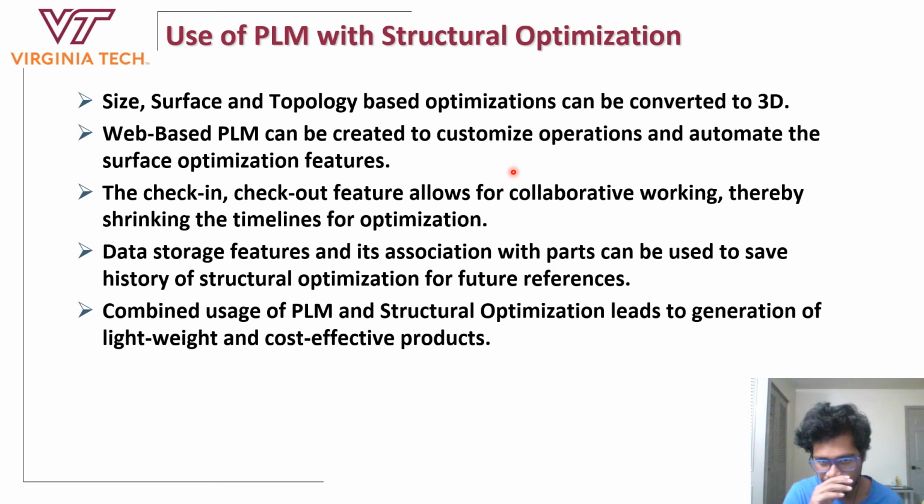The other thing to note is that when we bring PLM into the picture, we have features called check-in and check-out. Basically, we have an entire database in which all the data has been stored. And if I as a user want to work on a specific product, I have to check the object out of that data and into my workspace. So what this ensures is that there is a single master data. If I am working on it, someone else on my team will not be able to edit the part. So that is the feature that comes into play when we use something called PLM.